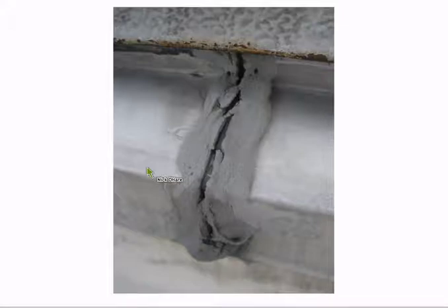Well, with your sheet metal flashings, there's so much expansion and contraction in there. If you don't have the adequate overlap on it, it's going to expand beyond its capabilities of keeping the building watertight. Try to put your sealant in between your laps. I would never put it over the top. Just the sun, the UV rays, the weather's just going to deteriorate that sealant faster than anything else. Mm-hmm. Yep.